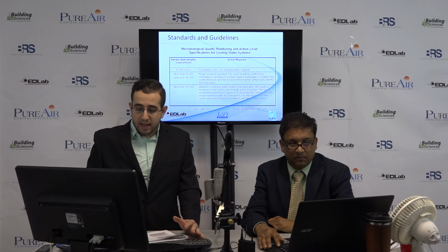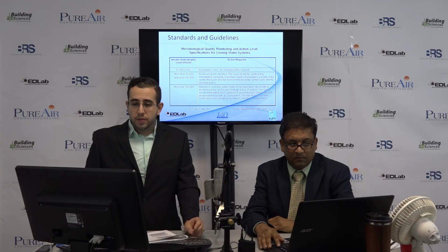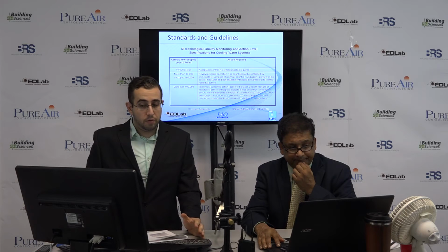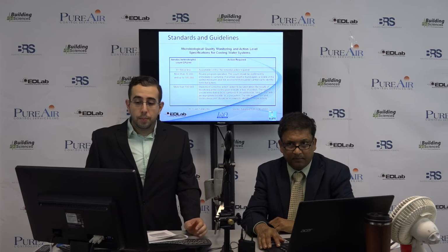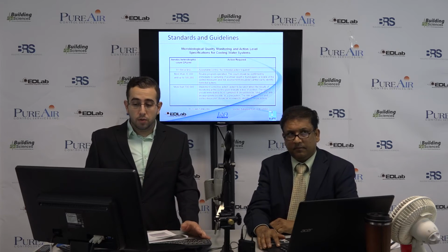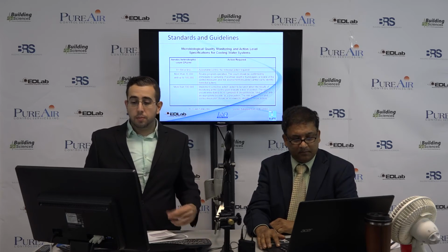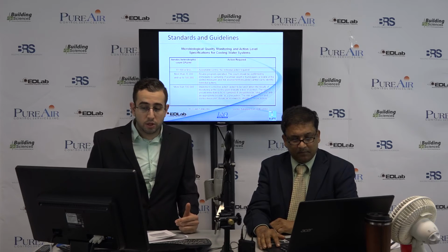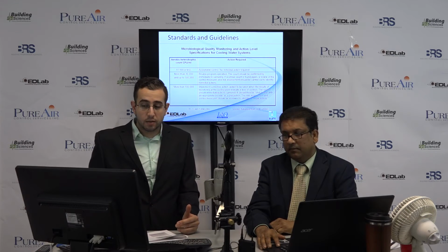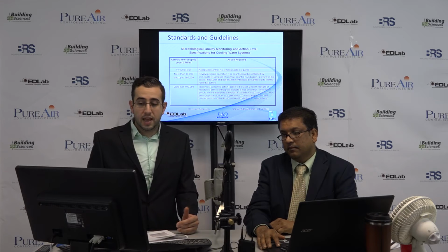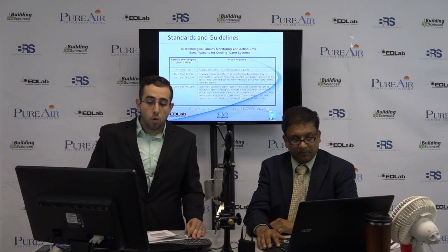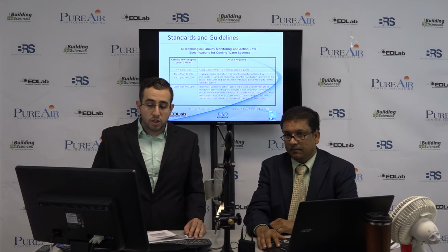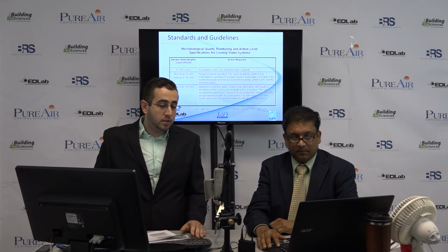This one is by the HSE, the guidelines. These are for cooling water systems. If you have 10,000 or less colony forming units, that's considered acceptable. More than 10,000, but up to 100,000, we have to review program operation. This needs to have resampling performed just to make sure that Legionella was detected properly. If that is the case, then control measures and a risk assessment need to be performed. And if there's more than 100,000, then corrective action needs to be implemented and further steps need to be taken.